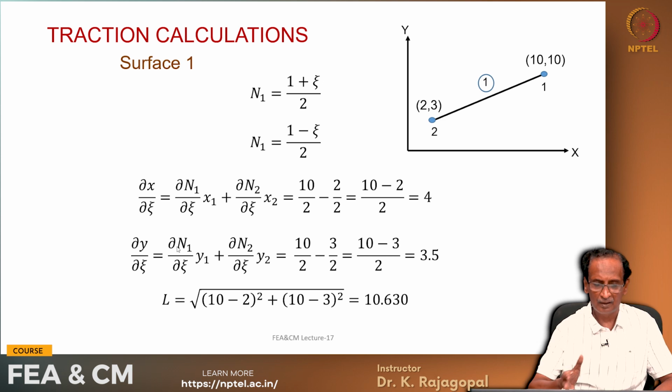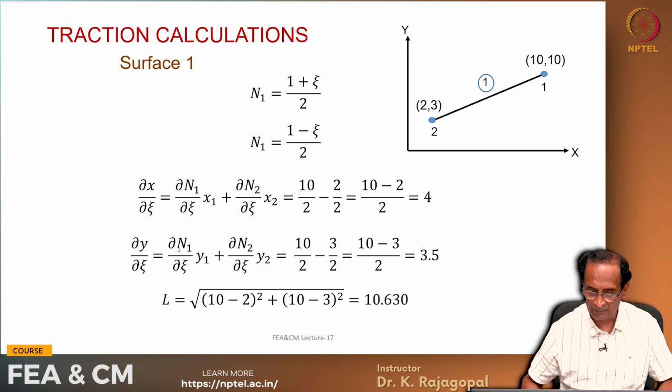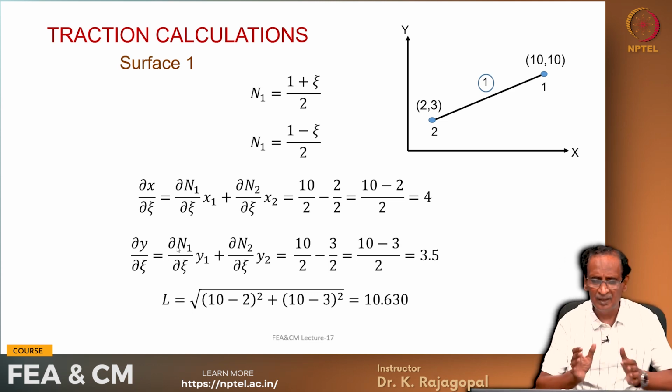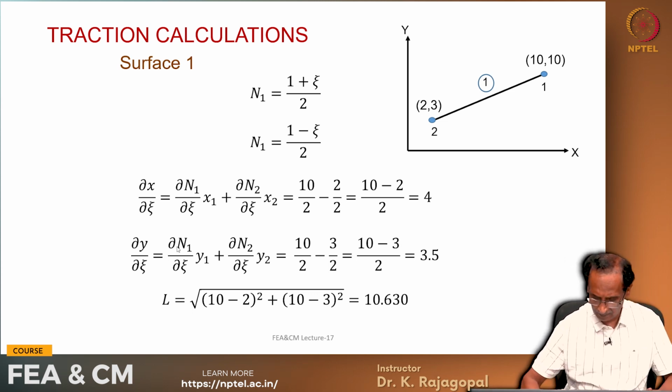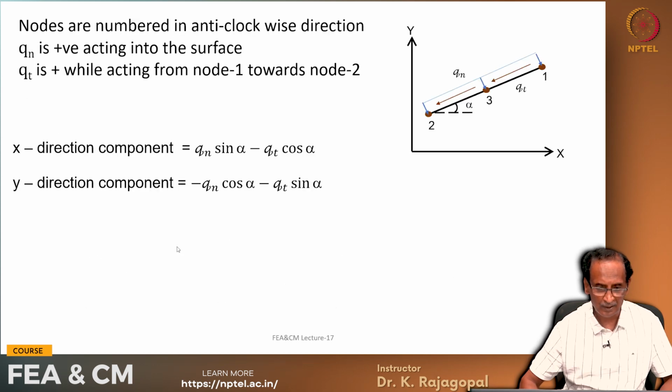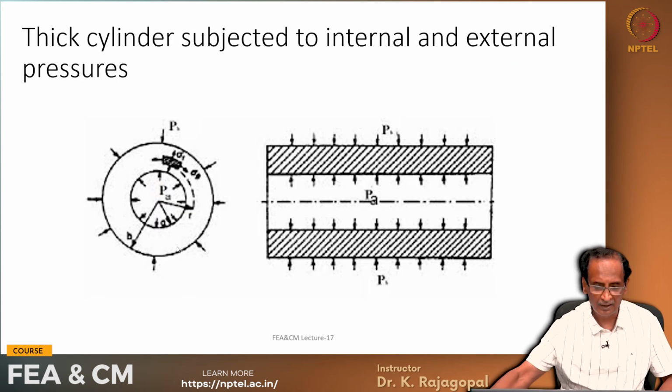These are all different numerical examples that you can follow, and if we implement this algorithm in a computer program, it can automatically take care of our pressure acting in different directions. Like on the circular surface, the pressure value is the same, but its component acts in different directions.